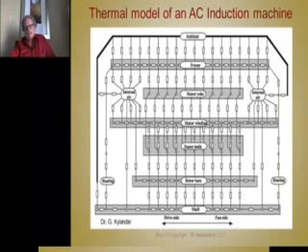The problem with these kinds of lump parameter thermal models is that there are so many variables that you don't know what to put in the circuit. You don't know what values to put in for these things, because the biggest problem is thermal transitions from one surface to another. For example, you've got a stator and you've got slot liners in it. Well, are the slot liners touching all the conductors? Are the slot liners touching the slot all the way around? No, never, and it varies from one machine to the other. So the ultimate temperature of the machine will be right, but the time scale of these different components of the machine won't be right. So that's the biggest problem with that. So you still have to take measurements of this.